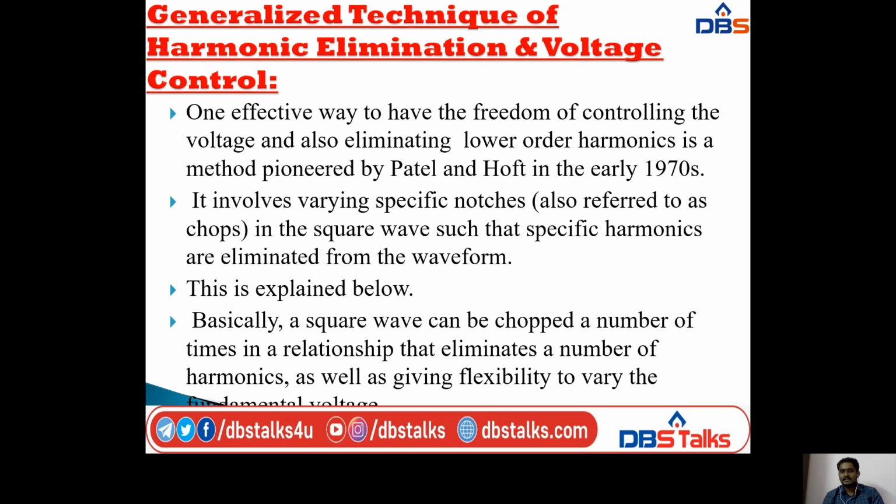It involves varying specific notches, also referred to as chops in the square wave, such that specific harmonics are eliminated from the waveform.